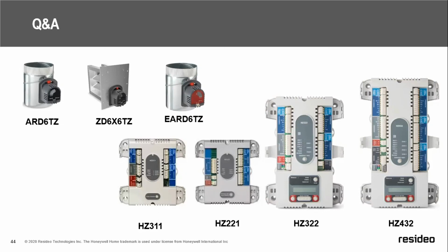Yes, for the 2.0 RedLINK products, if you want to control them over the internet, a gateway has to be in the loop in some way, shape, or form. The only workaround is the 3.0 sensors on the T10. I think that's a trick question, because RedLINK 3.0 is a Wi-Fi thermostat. So yes, you do not need an internet gateway on a T10.